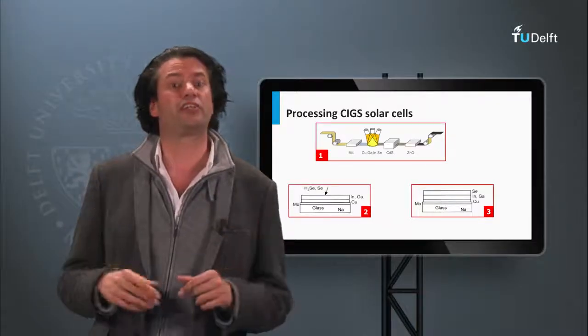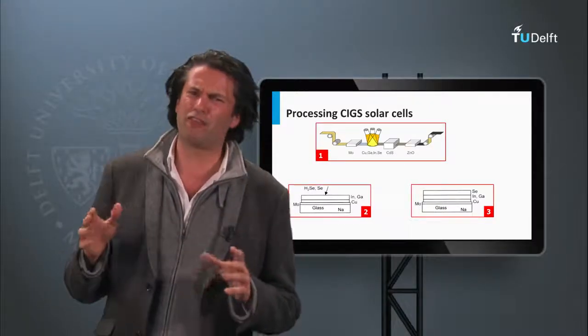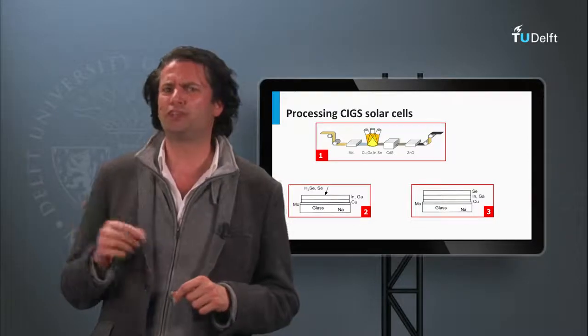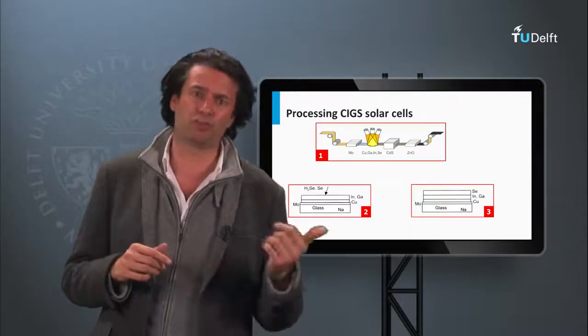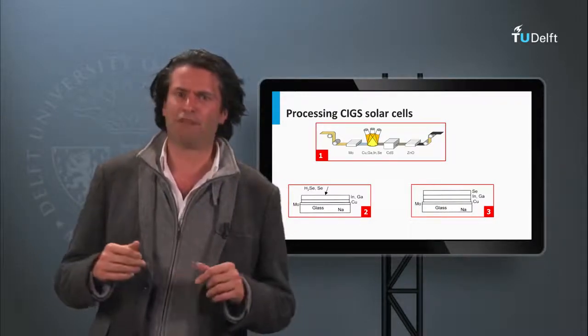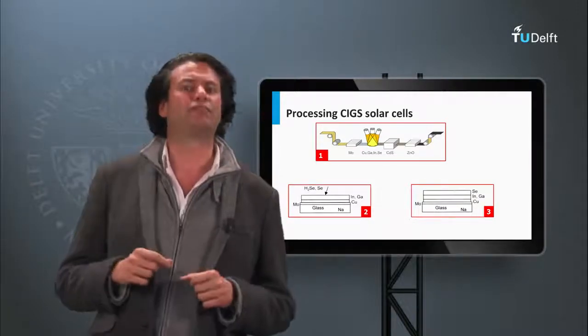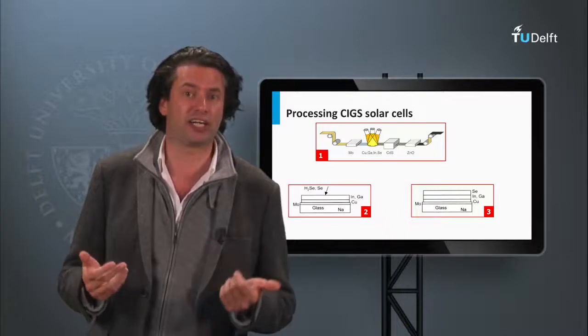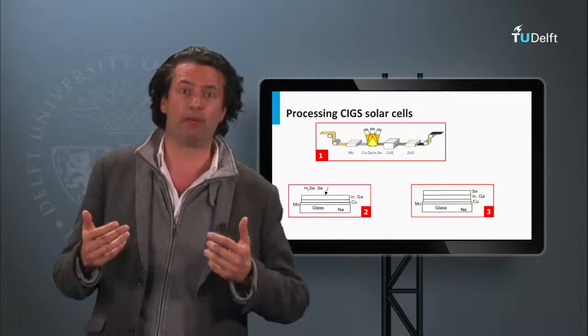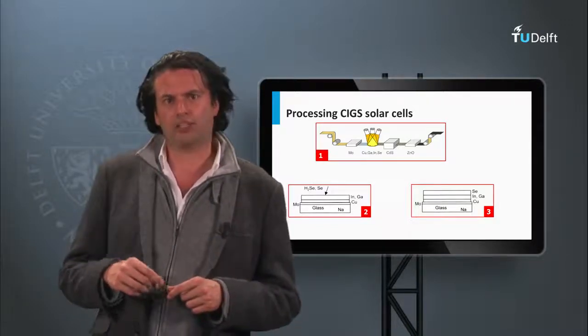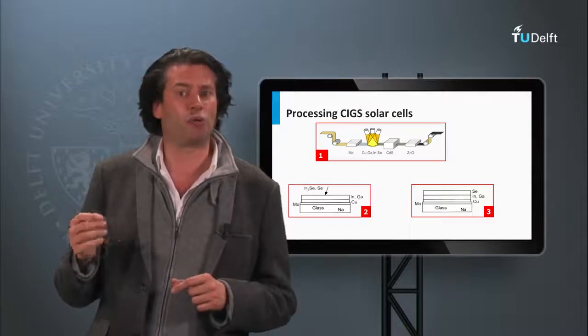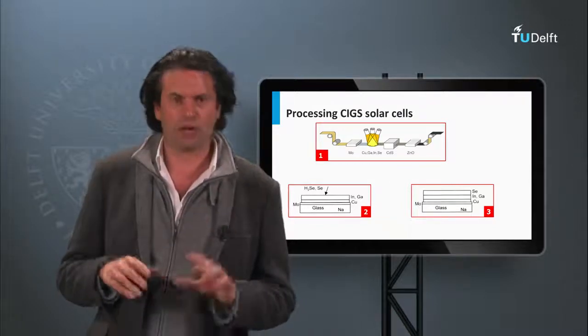An alternative approach is based on a kind of wafer bonding technique. Two different films are deposited on a substrate and superstrate. The films are pressed together under high pressure. When heated, the film is released from the superstrate and a CIGS film remains on a substrate. This processing technique is used by the company Heliovolt.